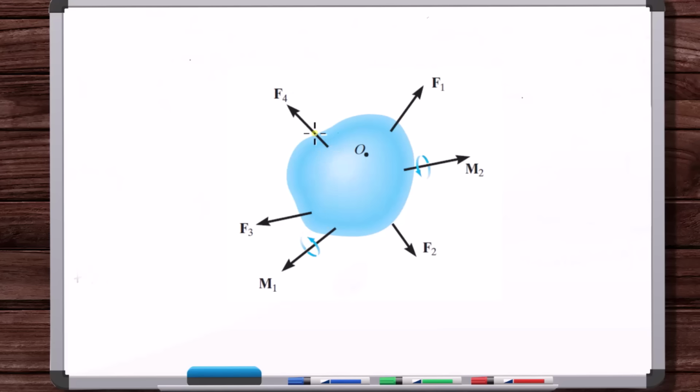You've got force vectors applied in 3D, and you also have couple moments applied in 3D. That is the general free body diagram. Now notice these are couple moments, and there are no moments like we talk about moments about a point, those are fixed vectors, or moments about an axis. Those don't exist on a free body diagram, at least the initial raw free body diagram.